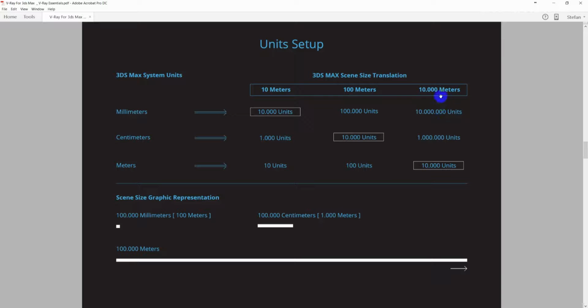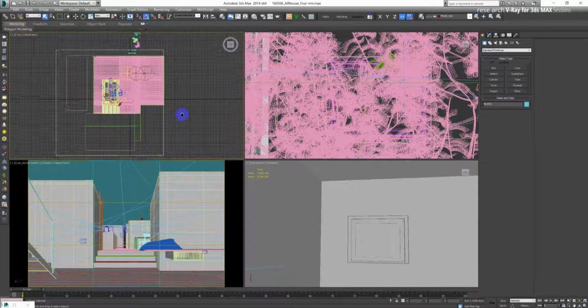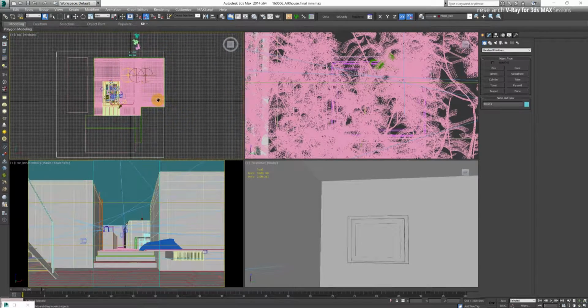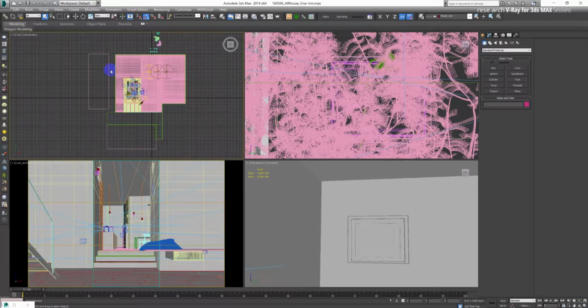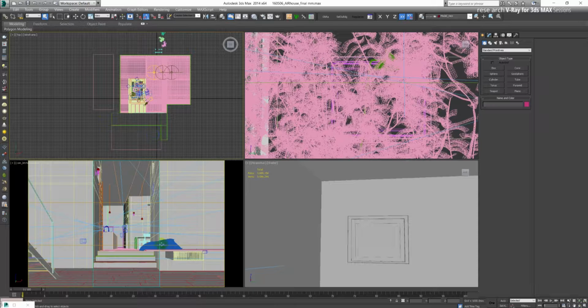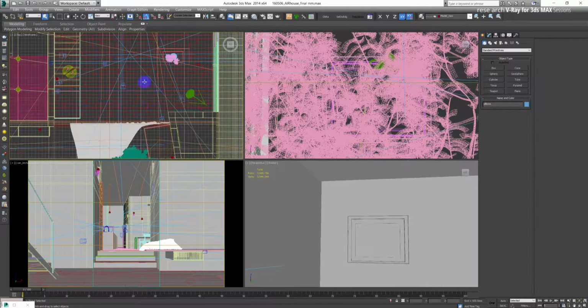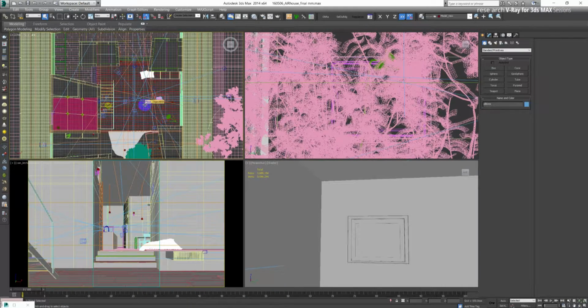I think it's starting to have problems on millions. So it's for sure better safe than sorry, but 100,000 is still quite okay. But to be honest, I was hesitating whether to use centimeters or millimeters, because what you can still do is model your general model, like the environment, in let's say centimeters or in meters, and do all the small detailed modeling, like the pillows or other very detailed models that are in your scene, in a separate scene and re-import that. We re-import them exactly the same way as I did in the previous step.